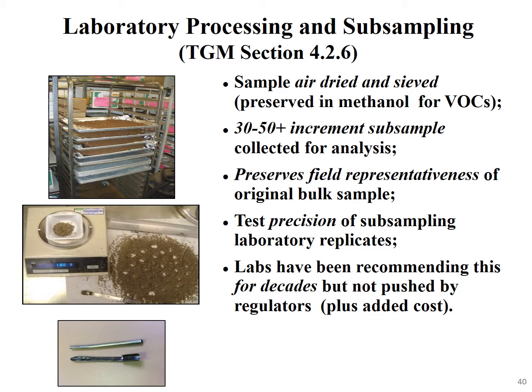This tool here is simply a metal straw, and if some samples are ground very fine, you can actually use that like a coring device, putting it vertically into the fine grained soil and coring it, and it'll stay in. If you put your finger on the top, it'll stay in the core, and then you can release that and collect your cores that way with really fine grained samples.